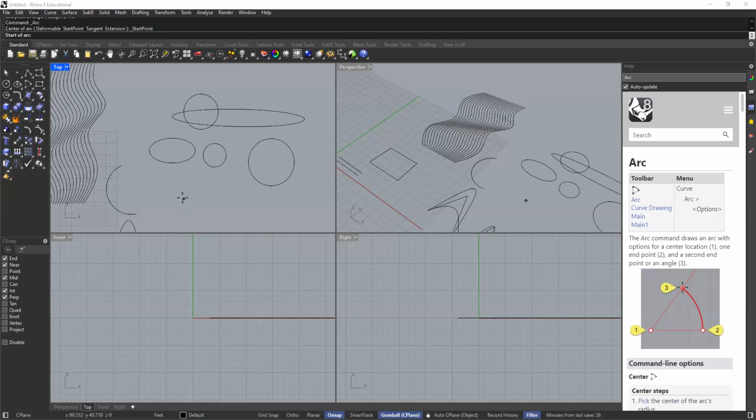So let's go ahead and click on this one. So it's the start, and again, the commands are up here, or what it's asking is up here. It's the start, then the end of the arc, and then the actual angle of the arc, right? So these are all very useful ways of creating a lot of these 2D commands.